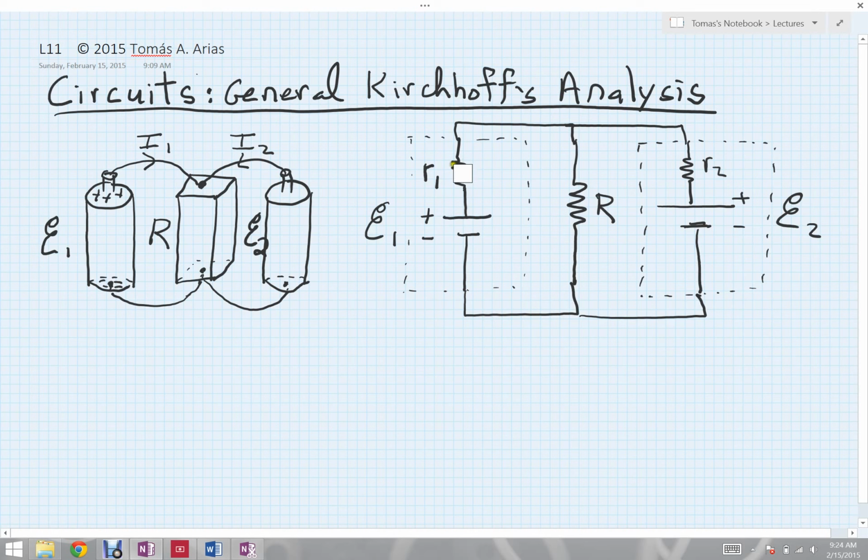You also might think of R1 and R2 perhaps as running in parallel to one another. The parallel combination, as you know, needs the total current going through the system to be the sum of the two currents. And certainly I can imagine that if I have current I1 from battery 1 across the top here and current I2 from battery 2 across the top over here, the total current flowing through these two internal resistances is the sum of those currents.